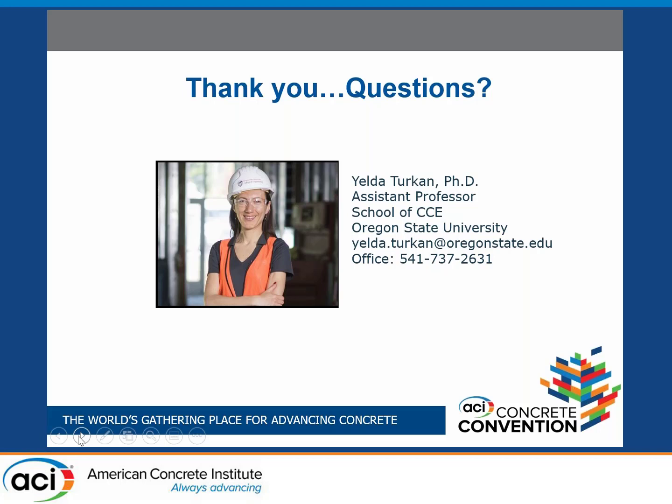Okay, great, thank you. The next question is, what type of targets are used with drones as compared to targets using the Leica scanner? Similar. Again, you can also do point cloud based registration together, but usually regular targets, as long as they can be seen in the point cloud, so that in the point cloud processing software, those targets are used to register those points together.